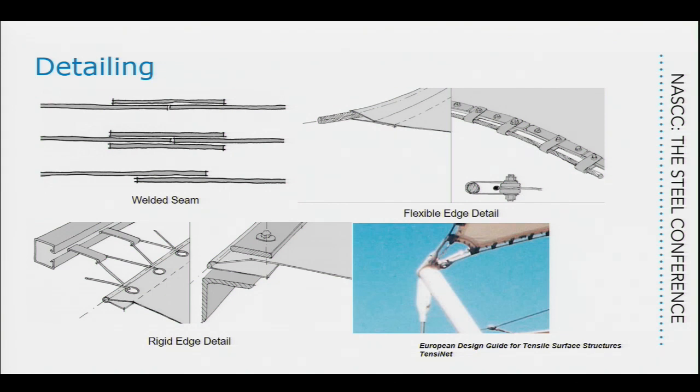So there's a deformation that happens there that is not due to the strength of the material, it's basically just taking out the slack. Then you get to a point where the material is taut, and then you start counting, so you have to load both parameters into your analysis. It'll say, okay, I've reached my apparent modulus of elasticity, now I'm deforming for the actual modulus of elasticity.